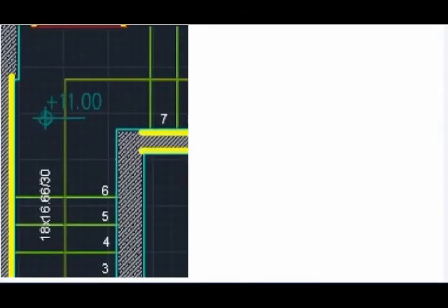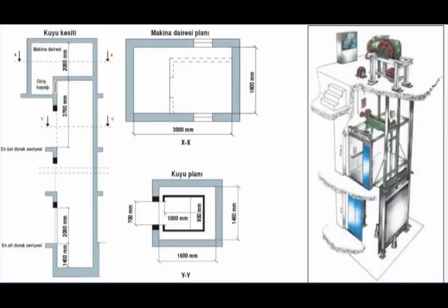We have talked about this, and we talked about the coding here. Here is the elevator room. Am I right? This one. The elevator room, look at here, is here. So this is the elevator room, okay? But the elevator room, as I told you, should be 1 meter up. And if you put 1 meter up, then this part should be at least 2 meters, okay? 2 meters from the roof to here, and 1 meter at least here.